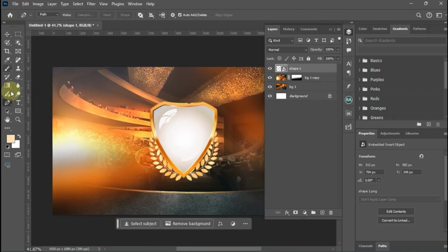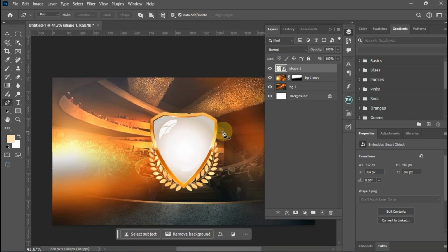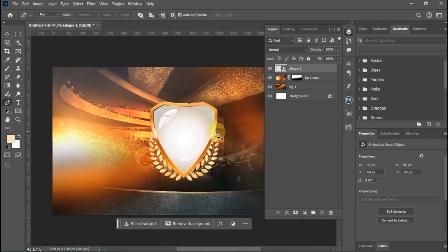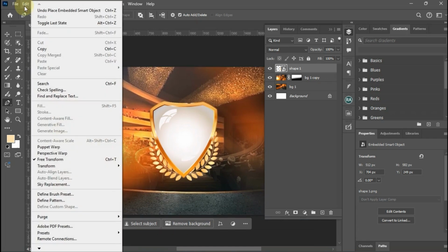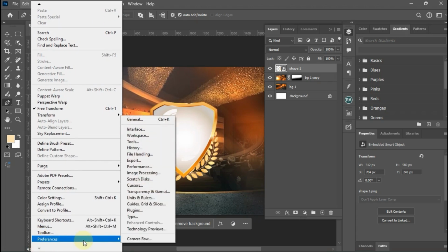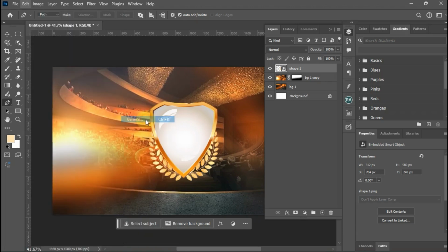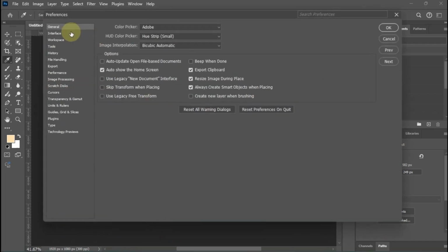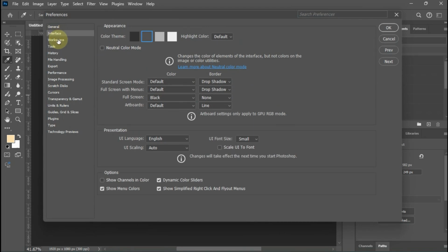So what you should do is just go to your pen tool. Okay, you can trace through this shape, trace through nicely. But let's go to your preferences. You have to change your zoom, because by default you have to hold Alt then scroll wheel. Now I want to be zooming just with the scroll wheel only. That is very handy and faster to trace this image.